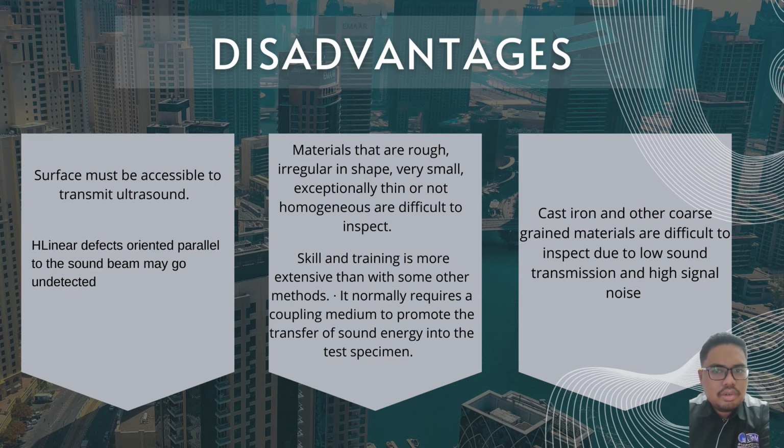Skill and training is more intensive than with other methods. It normally requires a coupling medium to promote the transfer of sound energy into the test specimen. Cast iron and other coarse grained materials are difficult to inspect due to low sound transmission and high signal noise.